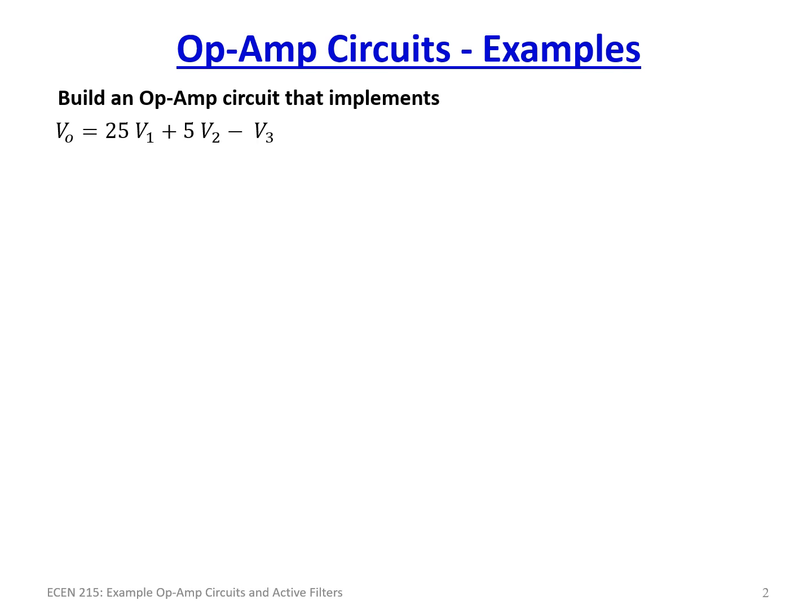Now, there isn't obviously a one circuit solution that does this, so we're going to have to cascade different ones. Looking at this, first of all, we notice that we have to multiply by a gain factor. We also look like we're adding, and then of course we're subtracting. So we're adding V1 and V2 and subtracting out V3. So overall this is a summation with gain.